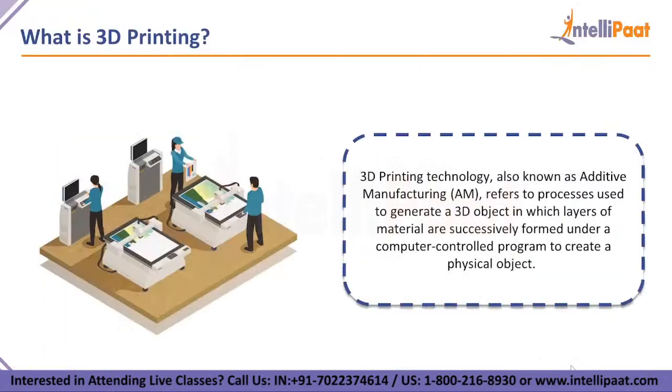3D printing is an additive technology used to manufacture parts. It is additive in that it doesn't require a block of material or a mold to manufacture physical objects. It simply stacks and fuses layers of material. It's typically fast with low fixed setup cost and can create more complex geometries than traditional technologies, with an ever expanding list of materials. It is used extensively in the engineering industry, particularly for prototyping and creating lightweight geometries.